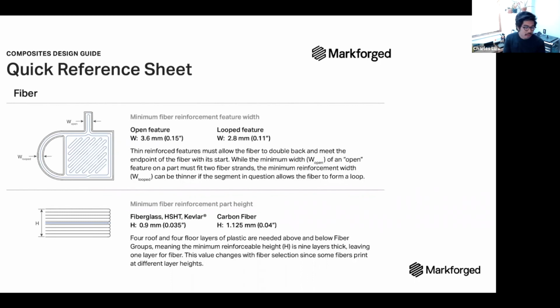Now, if you leave your material in open air for a day or even like 8 hours, then you're going to have some issues. So my advice would be to load it quickly into the dry box and then don't touch it again. The good thing with onyx is you don't really have that many options, because you're either printing onyx or another onyx. So I just tend to run the spools all the way out. And you don't need to dry it before.